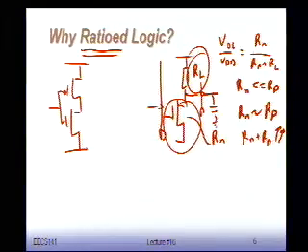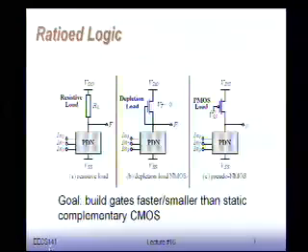Now, this is a simplistic vision. I could use a resistor. But making a resistor, current day technology is not very good at making resistors. I could put a strip of diffusion or some undoped polysilicon or something like that. But getting the precise value on those things is very hard. Also, it's not the perfect load. Actually, there's better ways of doing this.